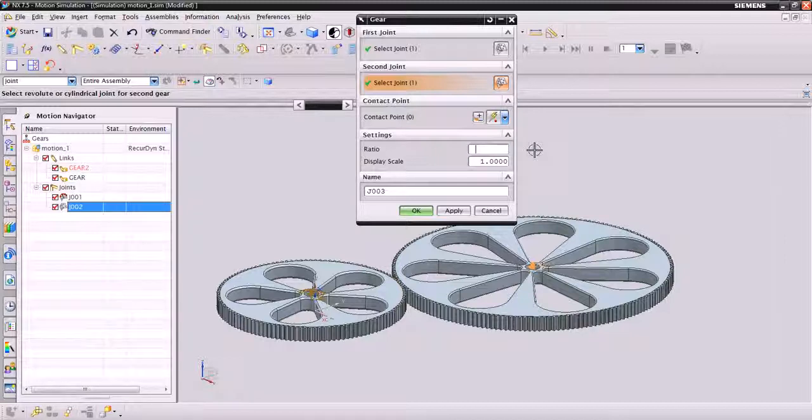Now, we have expressions in each of the gear part files for the radius, more specifically the diameter, but we're going to need to add a slight perturbation term for the size of these teeth. As it turns out, that term is 0.025 inches. So we're going to add that to the quantity diameter of gear divided by 2. That's the radius. And our second radius will be 0.025 plus diameter of gear 2. Click OK.